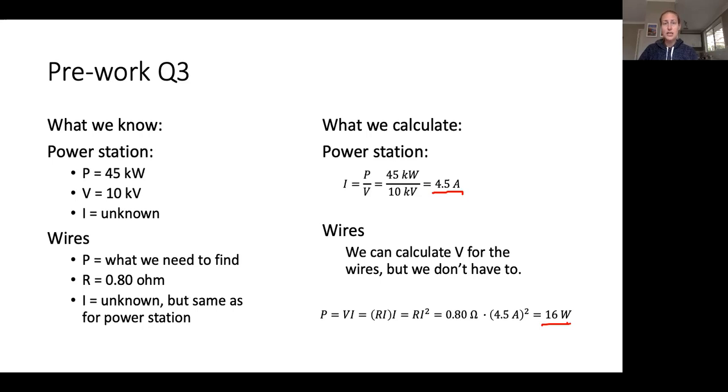And this is essentially the explanation for why we have high voltage in transmission lines. It's because the higher the voltage, the lower the energy loss due to resistance in the wires. And one of you asked whether there's anything we can do except use high voltage to avoid power loss in wires. And no, the main thing is really to keep the voltage high, but also obviously to have as little resistance as possible in the wires. But in reality, it's impossible to have zero resistance in those wires because the wires are made of something and they're kept roughly at normal temperatures because they're outside.